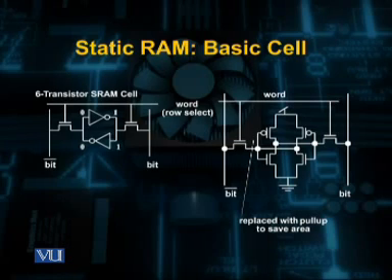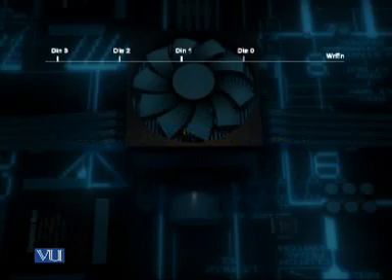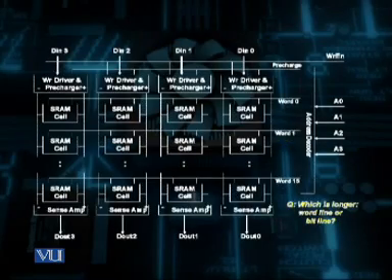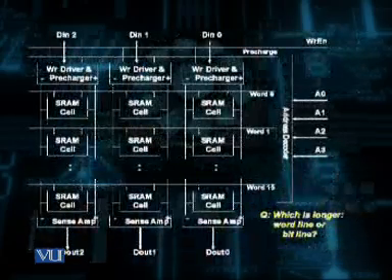Once these bit lines are charged to high, we will turn on these 2 transistors, so one of these inverters, in this example the lower one, will start pulling one of the bit lines low, while the other bit line will remain at high.